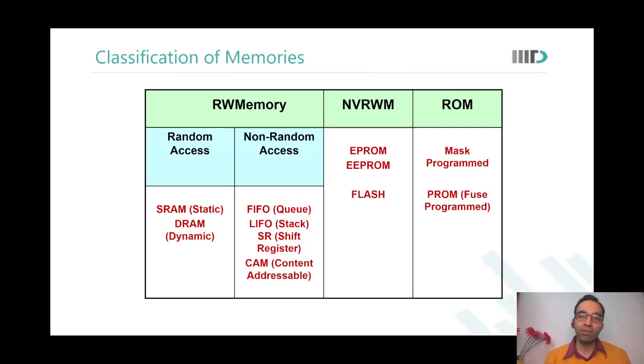What does that actually mean? Suppose my chip is manufactured in a slow lot. I now want to operate this particular chip or this entire lot at 1.14 volts instead of 1.1 volts, so that I get the required frequency. This is a one-time programming that you will do in the fab by blowing away some fuses. This is not about storing a new set of instructions or a particular set of instructions. Is that okay?